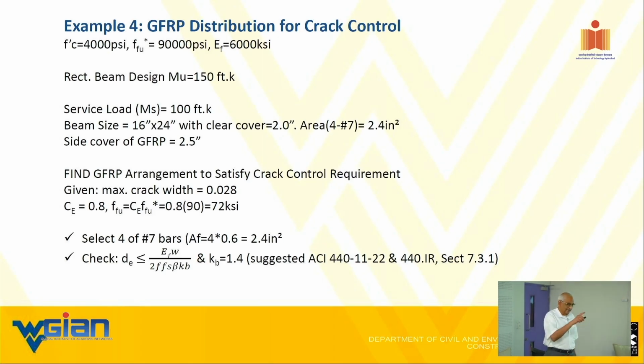That's why that tabular form is very important. Whatever the crack width control we are talking about, do not account for load factors like we do in terms of Mu. Okay, so you can go through that. The max crack width they're suggesting is 0.028. For our bridge decks, the crack width is around 1/3 of that. That's steel based, but we can relax that.